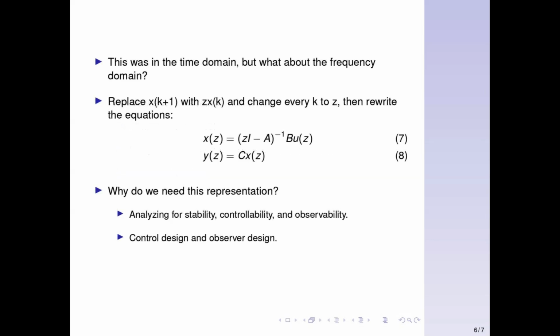The transition from the time domain to the frequency domain represents a fundamental mathematical transformation in the analysis of dynamic systems. It involves a substitution of the discrete time index k with the complex variable z, introducing a complex perspective that enables the examination of system behavior in terms of frequencies. The first equation encapsulates the evolution of the system's state, accounting for the influence of complex frequencies represented by z.